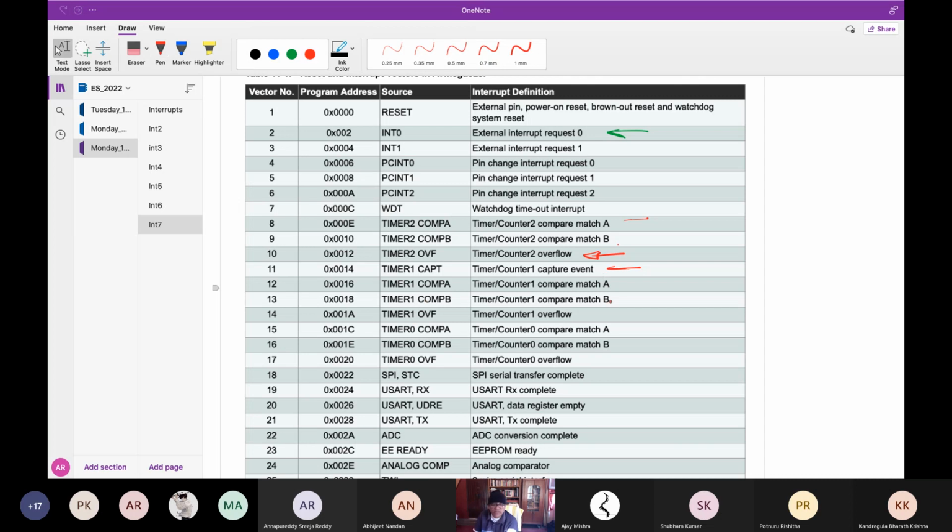We'll talk about timers, don't worry about them now. Using timers, you can really do many things. For example, you can do AD conversion independently. The timer will supply the clock and the interrupt will take out the data, automatically, very fast and at equal intervals of time. Polling is not required. In polling, if you write any code, the timing will be destroyed. You got it? So these are all reserved for timers.